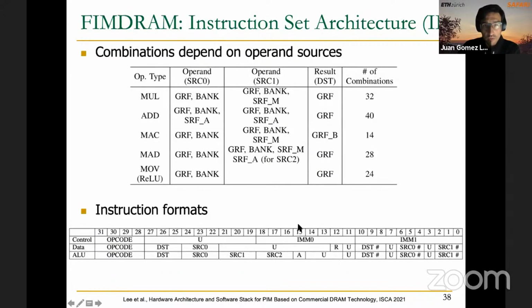And then remember that I mentioned that the move operation can also execute, not only move, but also these ReLU operations. So that will happen in case that this R bit here is set to 1 in the specific format of the move operation, which is this data movement format.